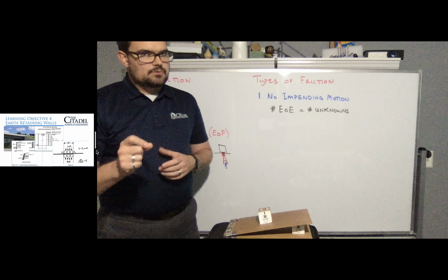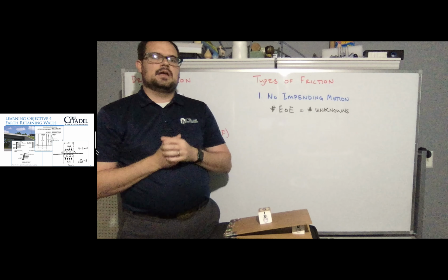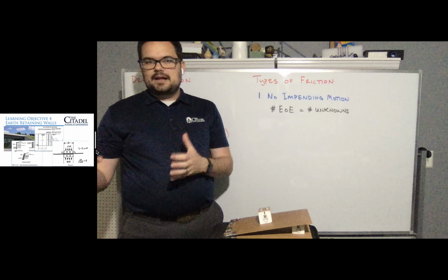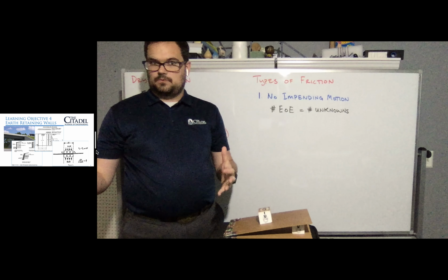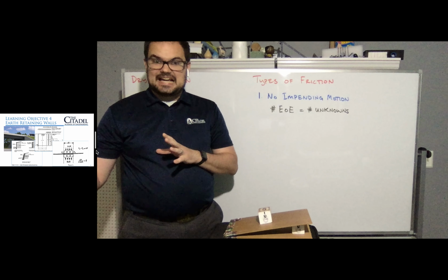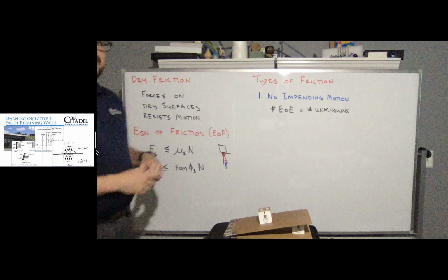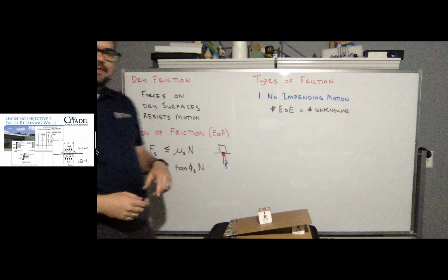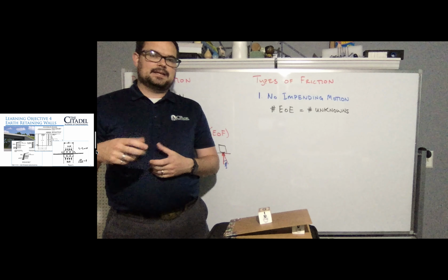So just to address it really quick, I know a lot of people think, oh man, but why doesn't contact area matter? I mean, my favorite example is that performance race cars have wide tires. So clearly that's to get more frictional force, right? Well, it turns out that the reason for that wide tire, and this is a little aside to frictional force, has to do with changing the coefficient of friction, not adjusting the amount of pressure acting on the tire.